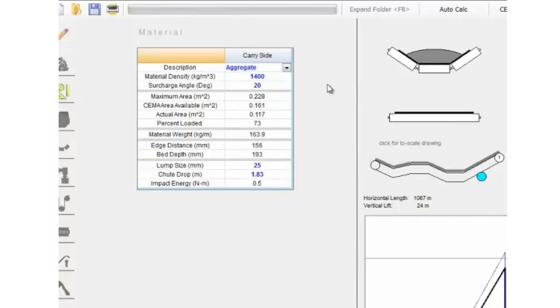A few things we want to make sure of is that we're not overloading the conveyor volumetrically, so 100% would represent the belt filled as much as you would ever want to fill it, and typically designers want to stay in the 80 to perhaps 85% range of what the manuals would consider fully loaded.